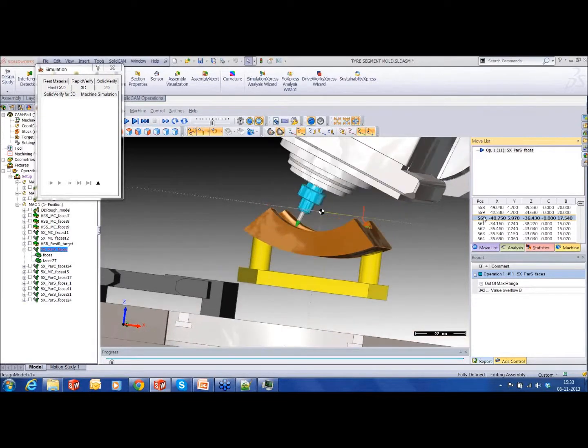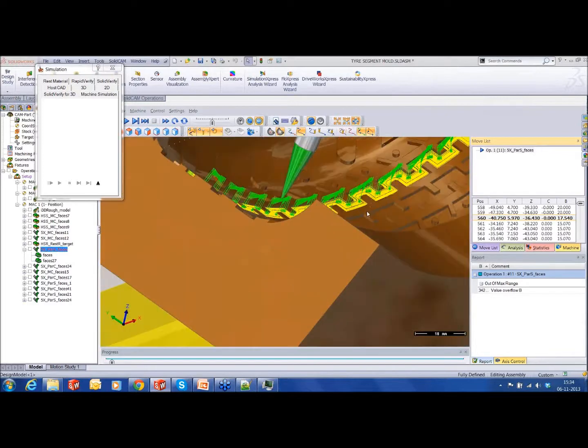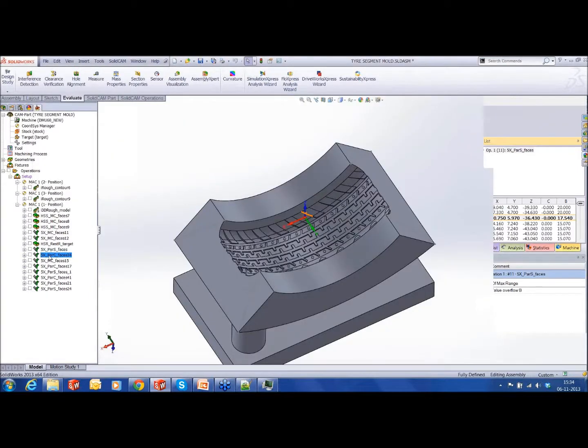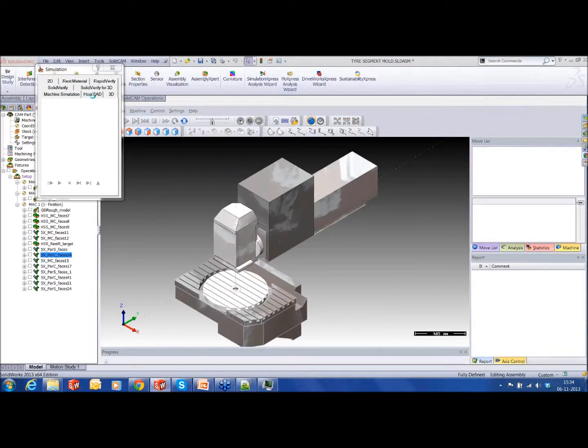So what we did now is to evacuate the center material of those ribs using 5-axis and a taper milling tool. Why taper milling is because we need to go into the furthermost corners as much as possible, so that's the reason I've used a taper milling, a taper flattened mill. Okay. After that is done, what I've done here is, if I run the simulation, not the machine simulation of course, I'm going to go into the host CAD.